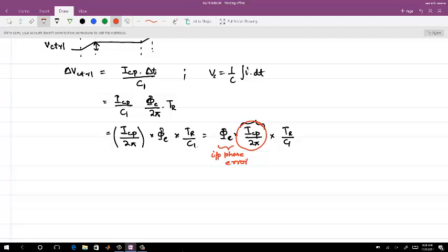Now the question is, this is linear only to the extent that your PFD is there. Say if the phase error is more than 2 pi, this will not hold, this is only in that range. So the thing is, your phase error detector output resets to zero. So the whole gain of the PFD plus charge pump will be like that.